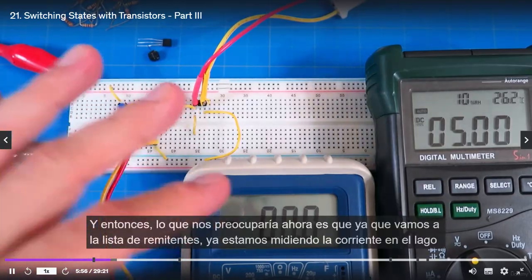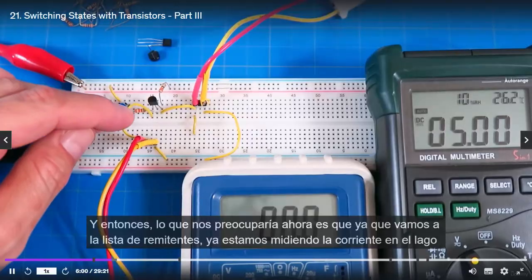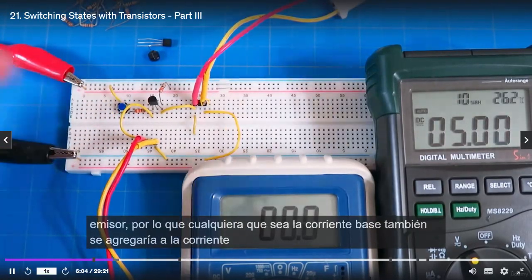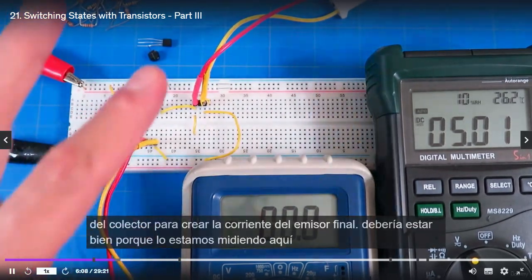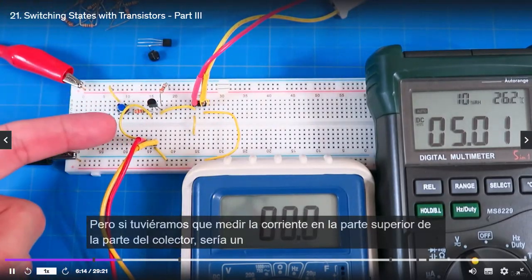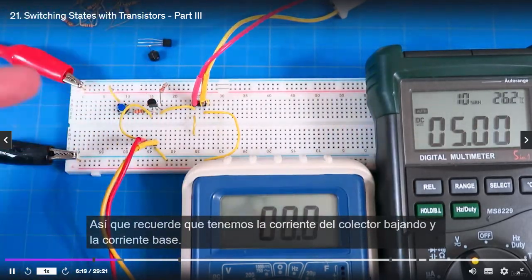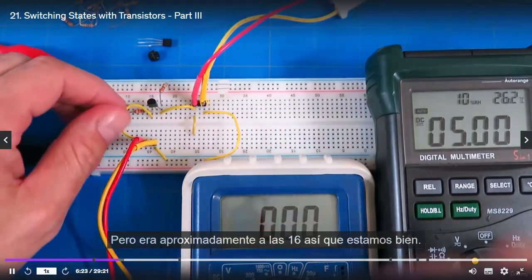What we would be concerned about is, since we're going in this emitter leg, we're already measuring the current in the emitter leg, so whatever the base current is also gets added to that collector current to create the final emitter current. We should be okay because we're measuring it right here. But if we were to measure the current up in the collector part, it would be a little bit less because we're not getting that base current added to it. So remember, we get the collector current coming down and we get the base current, and they both add up to make the emitter current. But it was at 16 roughly, so we're okay.